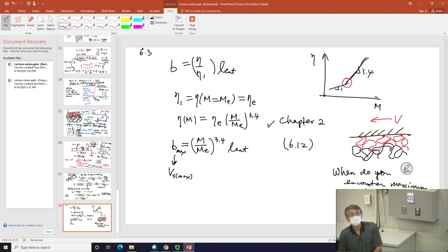This actually is something I need you to realize from the beginning. Number one, you probably could guess wall slip requires the Weissenberg number to be relatively large. Even Wi is perhaps not the best way, but close enough, because if you shear more slowly, the black chain can always rearrange around the red chains before anything even happens.